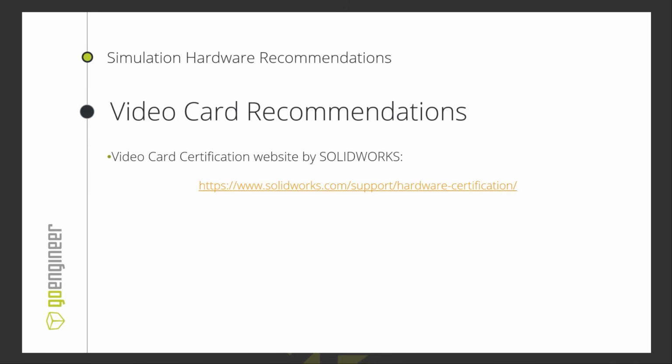And there's another one that says, does one versus two make a difference for large models for post-processing? Just in general for generating graphics, honestly, it's more about the amount of video RAM. I don't think there's any benefit to having two video cards for SolidWorks Simulation. There is for other stuff related to SolidWorks when it comes to rendering, but not for SolidWorks Simulation.